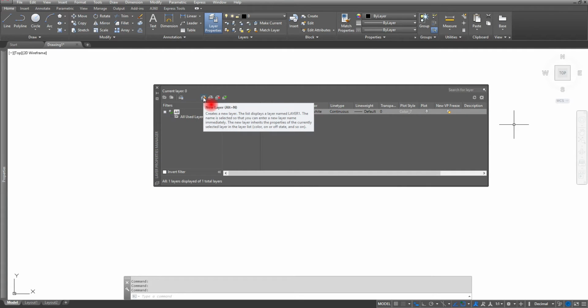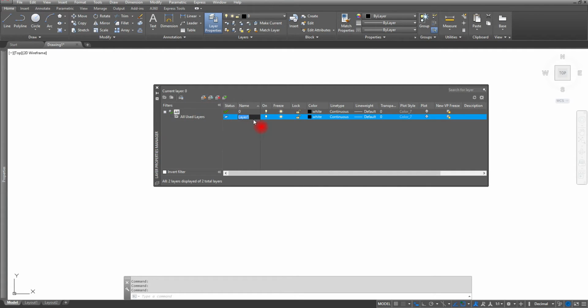Click on this first icon. Now you can see by default it's going to take the properties of the layer that I had selected. So everything that I had on that layer, it brings down to this layer. I'm going to type this one and make it the hidden, H-I-D-D-E-N layer. Okay, I'll hit enter after that. So now you see that it has created a layer named hidden.